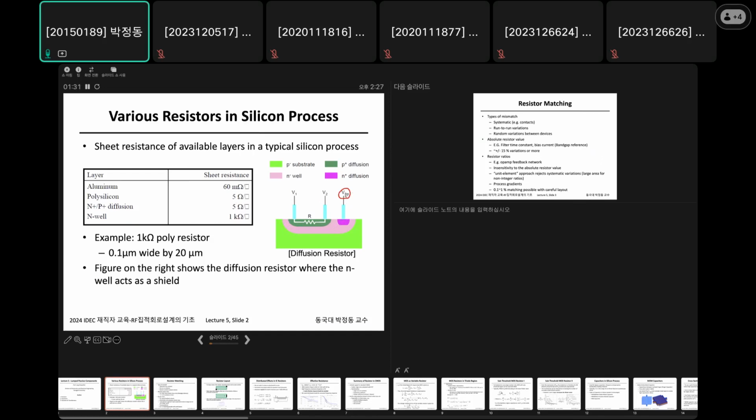So this is typically connected to VDD, right? I found that many students in our lab also do not use this external bias, but it is strongly recommended. It is because if you bias this into the reverse bias, then this can somehow provide a good isolation from the noisy substrate.